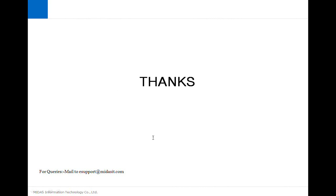We have a question from Mr. Aslan. If I do static analysis for an earth dam, can I do seismic analysis that includes static stresses? Yes, Mr. Aslan, you can do seismic analysis, first performing an eigenvalue analysis and then a time history analysis that will include static stresses.